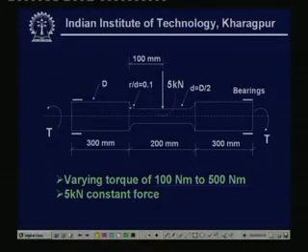The only thing we will have is a load factor, because in case of bending the load factor was 1, but in case of shear, you remember, the load factor comes out to be around 0.577. So, if we consider this design once again, taking up the torsion in addition to this particular 5 kilonewton force, then what we can find out very quickly is something like this.